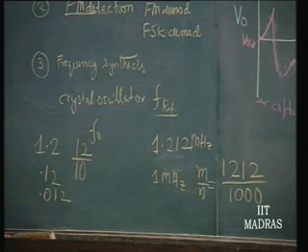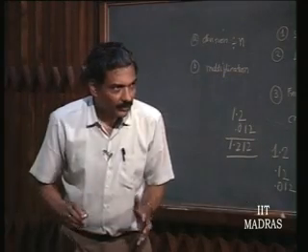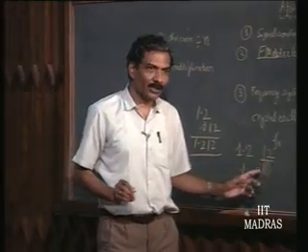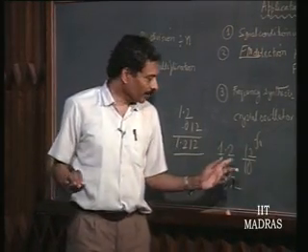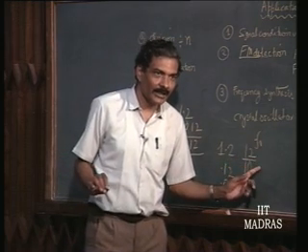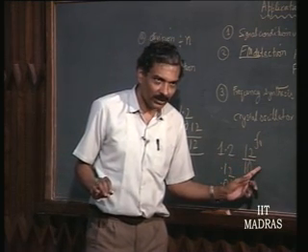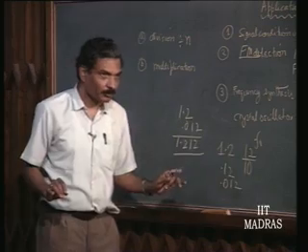Then I have to add 1.2 to 0.012 and I can get 1.212. This is the most efficient practical scheme of synthesis. Have you understood the difference? Okay. I simply use commonly available counters, decade counters as far as possible, and the only deviation I am doing is I am designing a divide by 12 counter in addition, which is also possible.